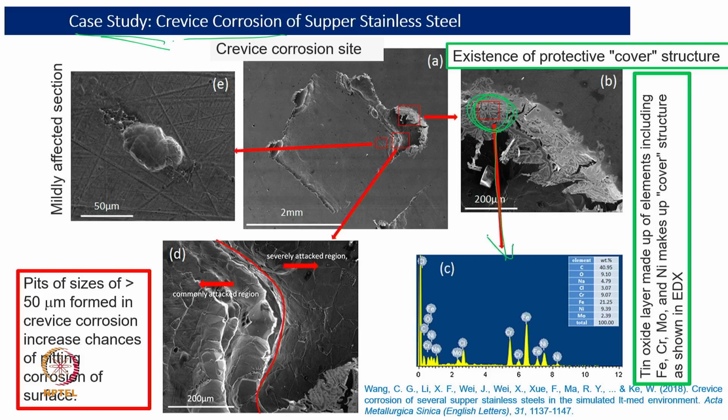And what is the chemical composition? It has iron, it has chromium, it has nickel also. So, those things were shown. Many times when we do a study of the debris, it can really provide very good information. If there is some sort of debris with a particle size of more than 50 micron, and particularly there are corrosion chances, we should act immediately, so that corrosion can be halted, can be stopped. Otherwise, there will be a brittle fracture and then the whole system will collapse.